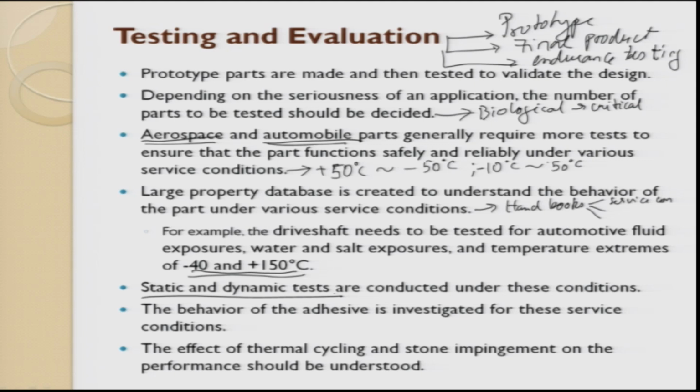Static cases, okay, we do a tensile test only for one component, but what happens as and when the component is dynamically loaded and unloaded? What is the response, the deterioration of this product or this property? This is very important. Today we have started looking into dynamic testing also. That means we apply a fatigue cycle or some cycle, compressive loads, tensile loads, compressive-tensile loads, so that we get the output. So static and dynamic tests are conducted, and then we try to take the conditions out.